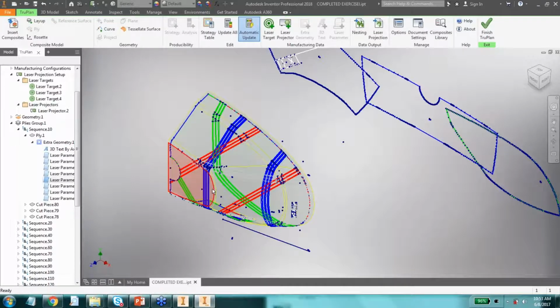So by passing the XYZ plus IJK vectors in the laser projection file, what we're doing is allowing the team of lasers you've got on your shop floor to make that decision actively and dynamically based on where that projector is with respect to the tool. So it's an automatic function that is included within the laser projection controller, and it's enabled by the fact that we're passing not only XYZ values but also IJK. So that's the automatic way to do it.